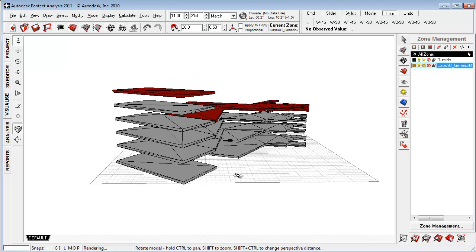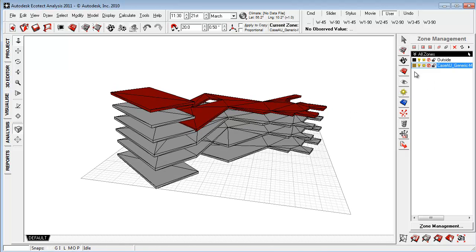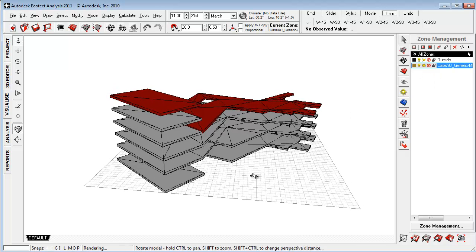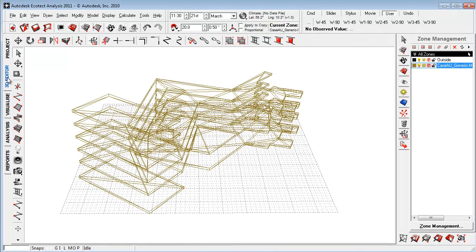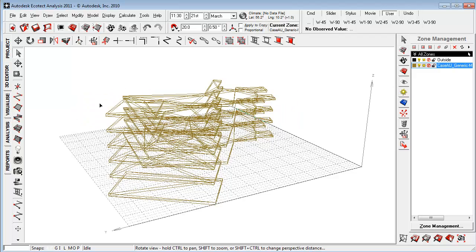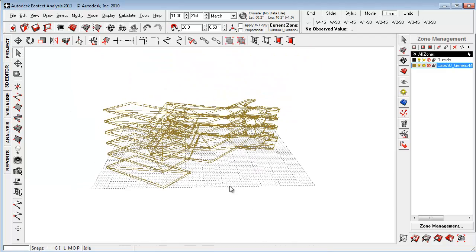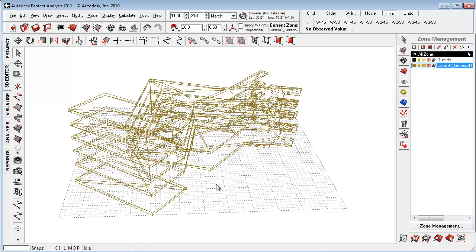First of all, it makes fewer triangles in the geometry, and it's a bit easier to handle and assign materials and just hide them or turn them off within Ecotech, because when we go to the 3D editor, these elements really have a surface on the sides and in the bottom and so on, because that's how geometry is within Revit, where this model comes from.